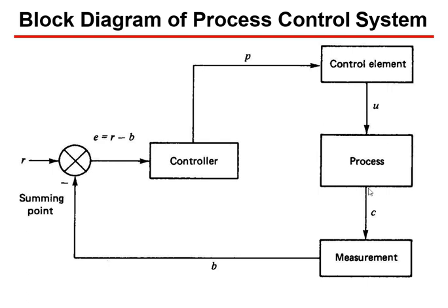Then the output is measured with a feedback element. So measurement is done here, and this is the output and a measurement is taken over here, and this is B as a feedback. And here there is a summing point. If the feedback is negative, then the error will be the difference between R and B. If the feedback is positive, then the error will be R plus B. So as per this sign, the error equation will change. I think you know this.